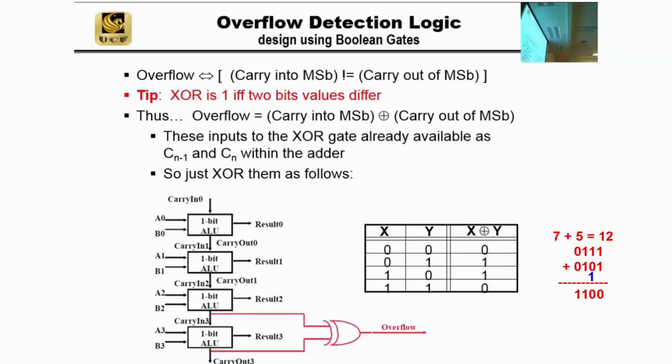We overflowed, see? It means we're overflowing. This is why it's into the MSB, and this is the sign bit. It has a special purpose. Is this the uppermost bit, the most significant bit of any adder? If it's 4 bits, 32 bits, the most significant bit is always keeping track of the sign. If you carry into the sign bit, game over, overflow. So let's look at this. What number is this? -4. So 7 plus 5, we know in real life, is 12, base 10.